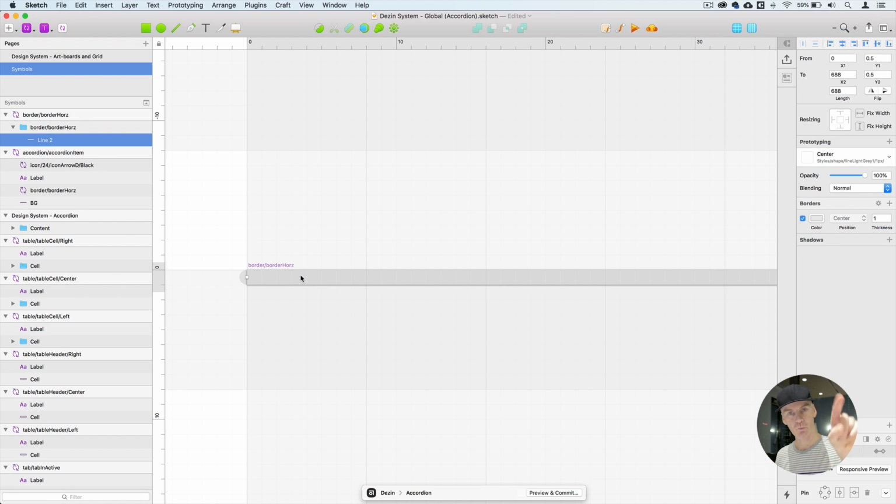Okay, but you can see that little round corner. We don't want that, we want a butt cap. So let's go over to the cog and the border, change it to butt and change this to butt join.